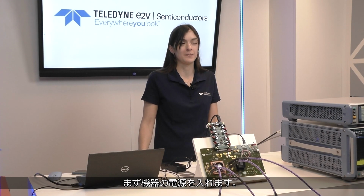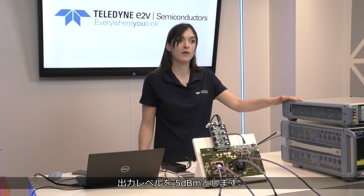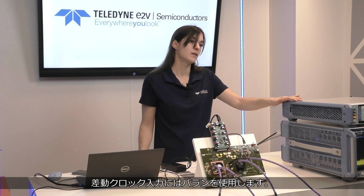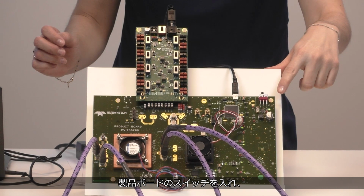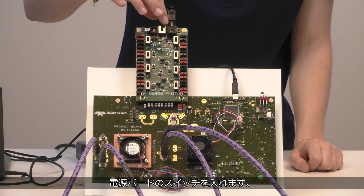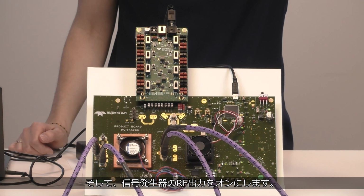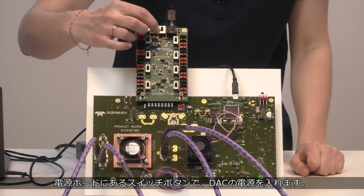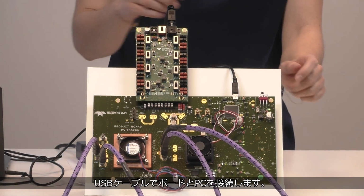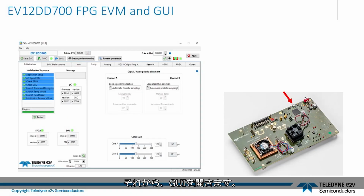Power up all equipment. I set the clock frequency to 12 GHz and the output power level to 5 dBm. A balun is used to provide a differential clock input. Turn on the product board. Turn on the power supply board, then switch the RF on the output signal generator. Power up the DAC using the switch button on the power supply board. Connect the board to the PC using the USB cable, then open the GUI.